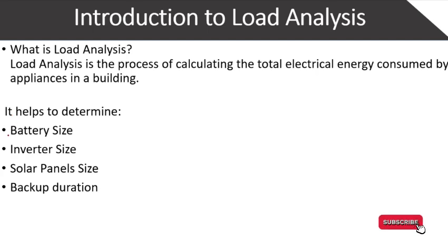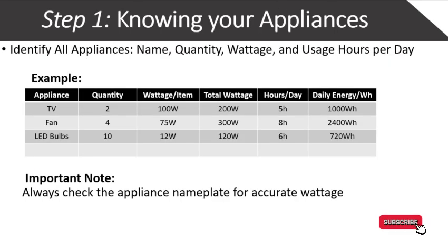Load analysis will help to determine the following: your battery size, your inverter size, your solar panels, as well as your backup duration. Now, the first step is identifying all your appliances, their names, their quantity, wattage, and how many hours they are being used in a day.